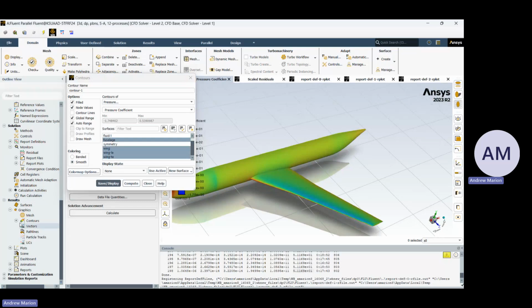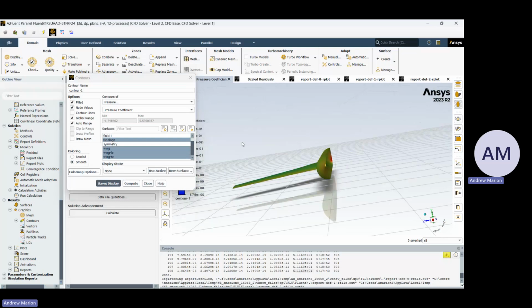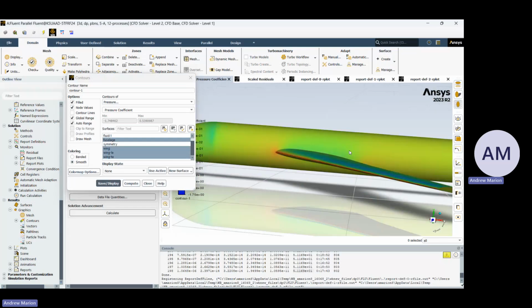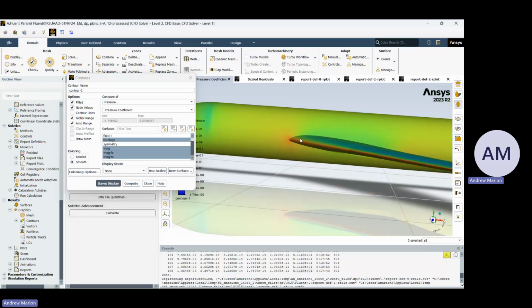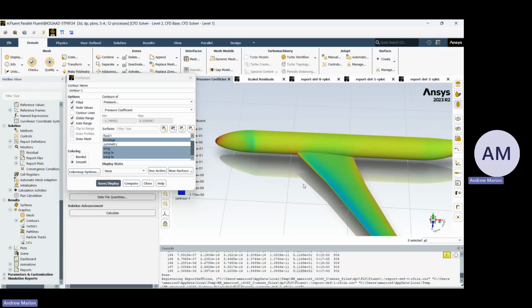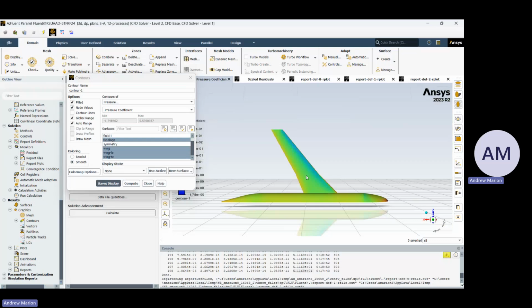The high pressure is going to be looking for an area to escape to get to that low pressure zone. It's going to travel along the wing, and you'll see there'll be spillage up at the top along what's called the wingtip, like this. That creates these wingtip vortices. If you ever see planes fly through clouds, you'll see these giant vortices coming off the back ends of aircraft. That's all from this one little small part on the aircraft, the little wingtips.